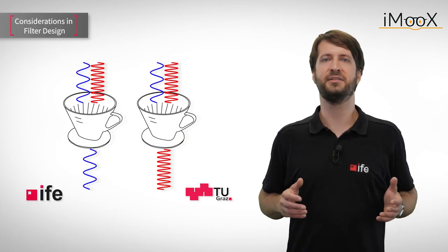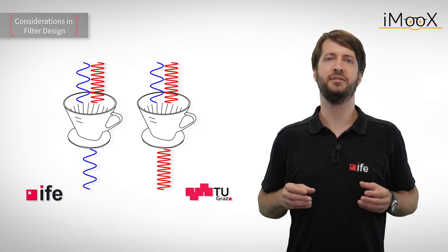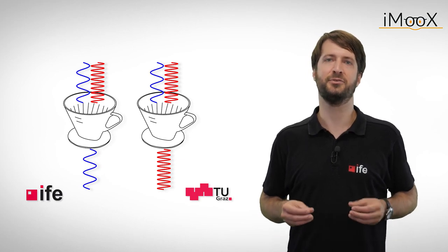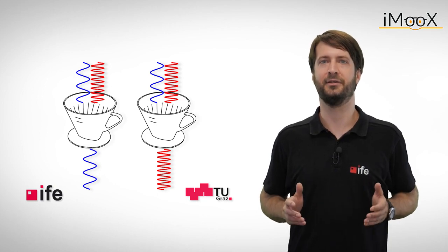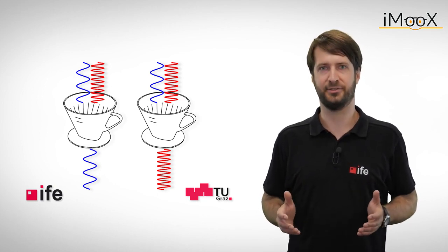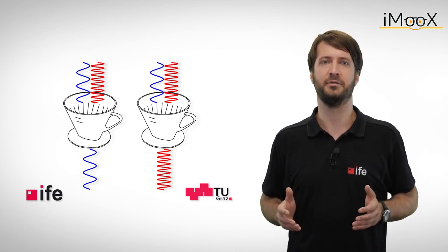You see, filter design is a challenging task. First of all, you always need to know what the purpose of your filter shall be. This will often lead to specific requirements. Usually, the first thing to think of is the corner frequency, followed by the steepness of attenuation. The latter will give you the order of the filter.